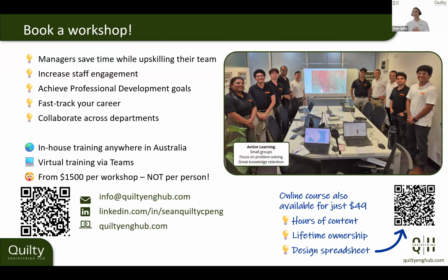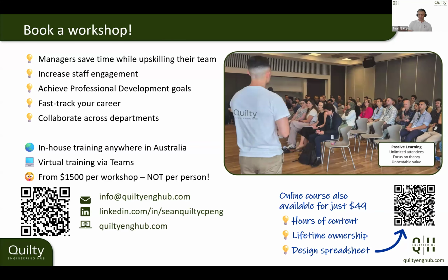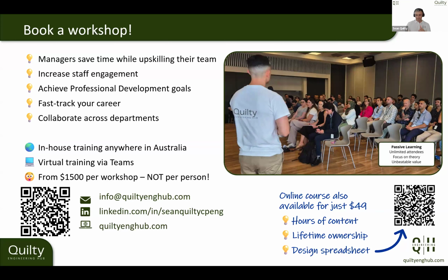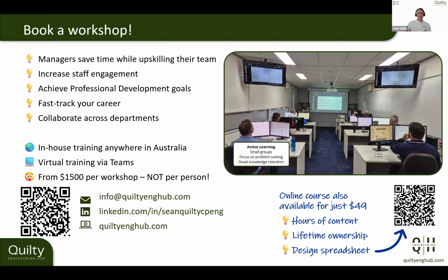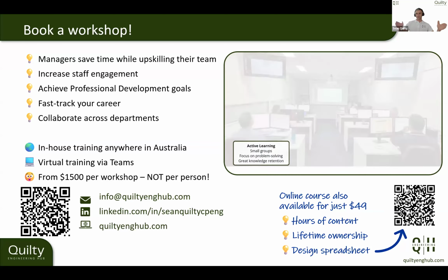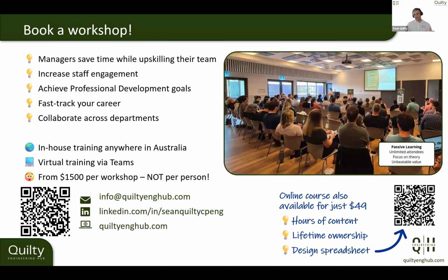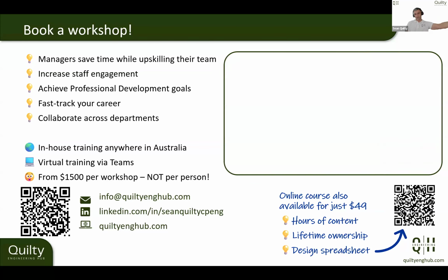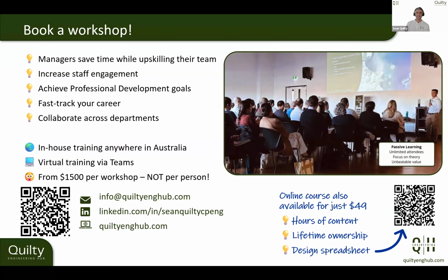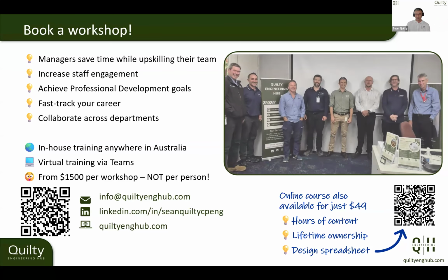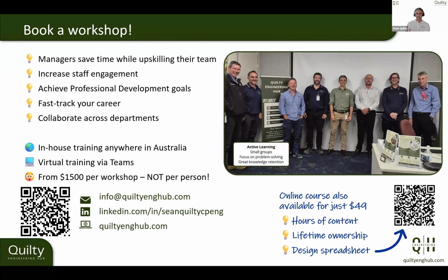It does change. What I would typically do in any of my channel designs, grass is a good example. If we're looking at a grass channel, there's going to be a couple of different phases. But if we look at the worst case, or the two ends of the spectrum, you would have it when council have just constructed, or maybe just maintained. Maybe they've gone in, they've just dug out a whole heap of sediments, a bunch of weeds, and they've basically stripped it right back. I would look at the condition of that channel and see what would go wrong.